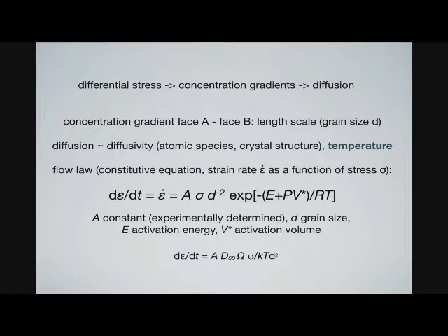And then all these other constants that are in there are really lumped into one. You measure stress and strain rate, you fit your data, and you get an exponent, or you get a pre-exponential constant A that contains everything else. Sometimes when people work with these equations in flow modeling, for example, that A is a little bit neglected, or parameters such as the activation energy.